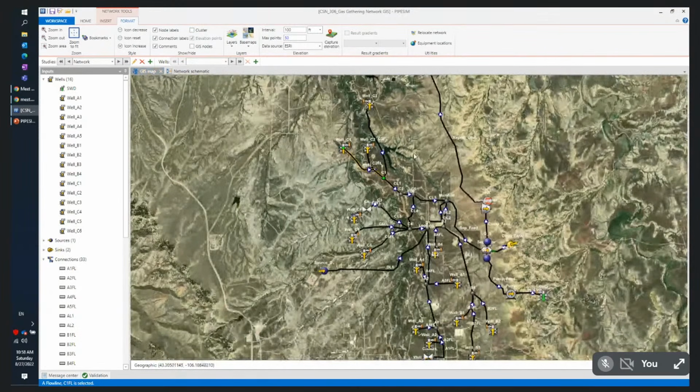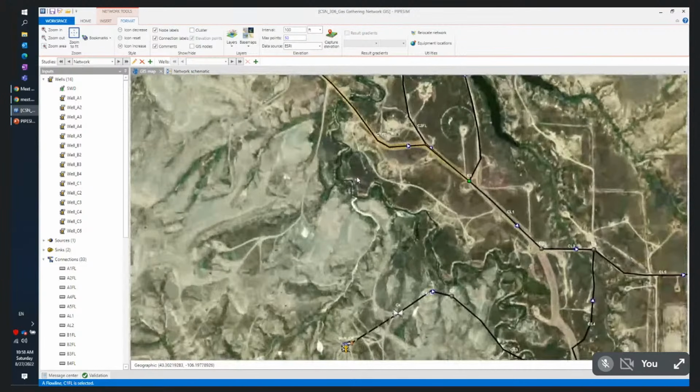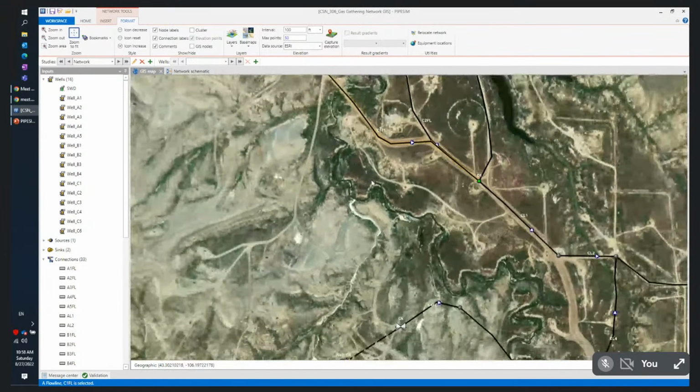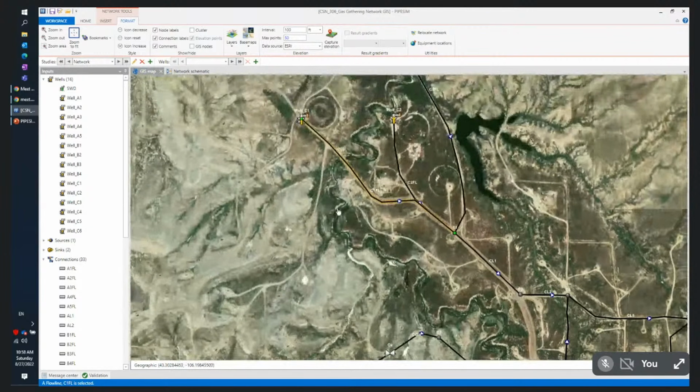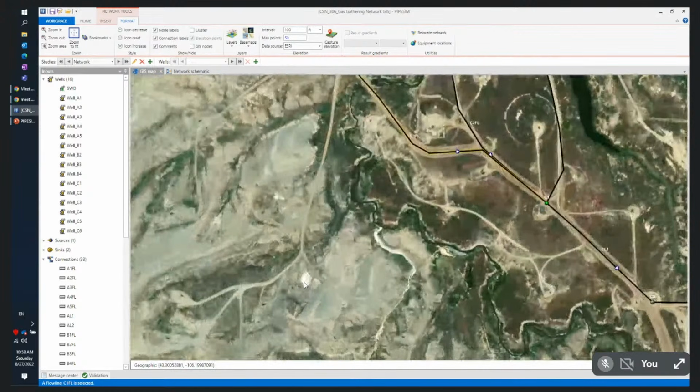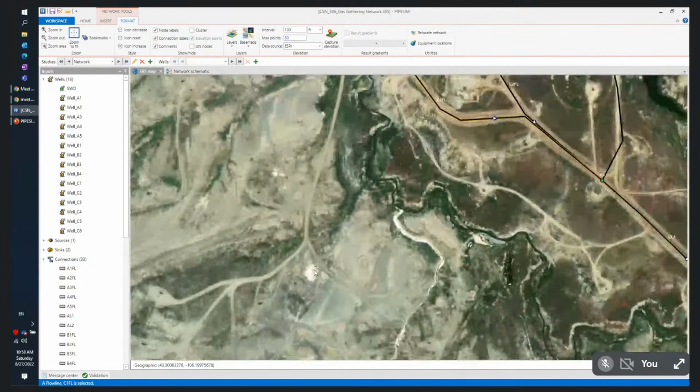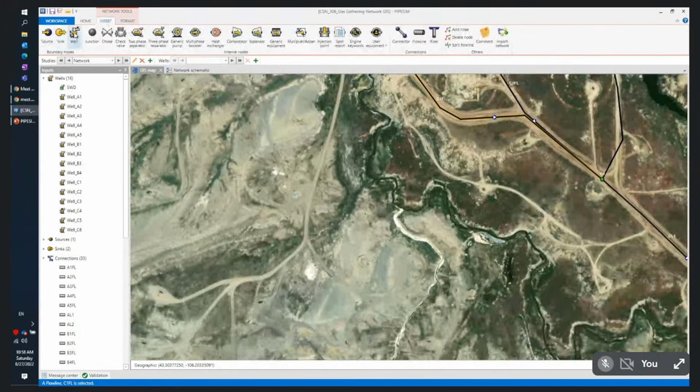And as you can see here, as I said, this is very useful for you. Now, suppose I want to drill a new well here, okay? How am I going to add a new flow line to my system? So let's say I have a well that's going to be drilled here. So what I'm going to do right now, I'm going to insert a well. Or in the beginning, let's assume that I'm going to insert a source. I don't want to enter the well details right now. The well has not been drilled yet. But this is where we have identified the well location.